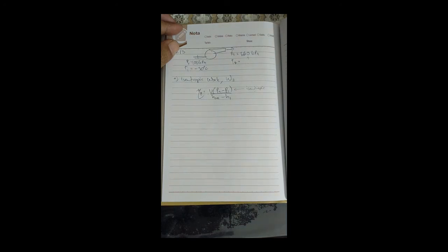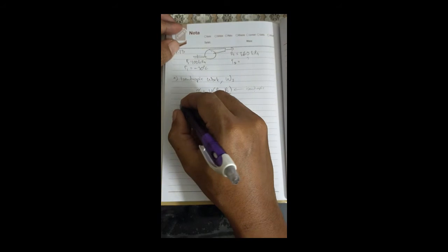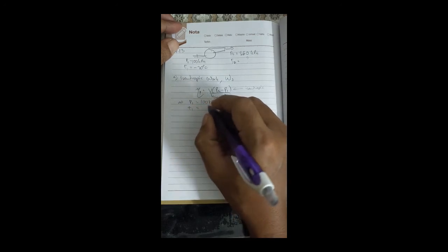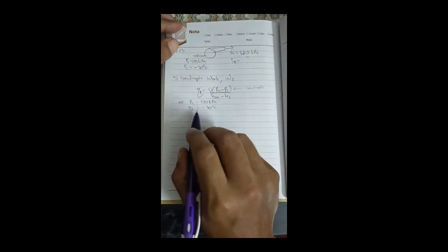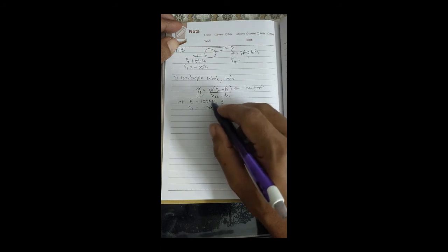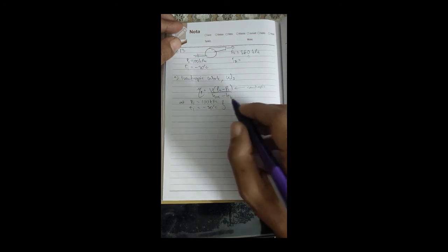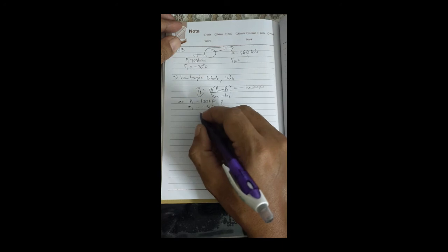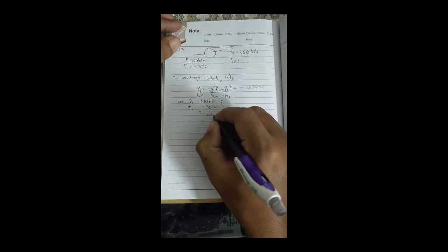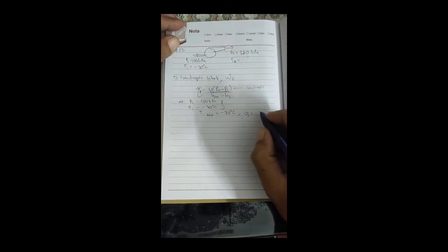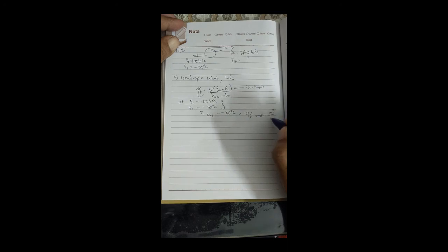The specific volume for the pump: at P1 of 100 kPa and T1 of negative 30 degrees C, we check the refrigerant tables. Normally it is a mixture, so using T1 saturated at minus 30 degrees Celsius, the specific volume v1 is vf, in meter cubed per kg.